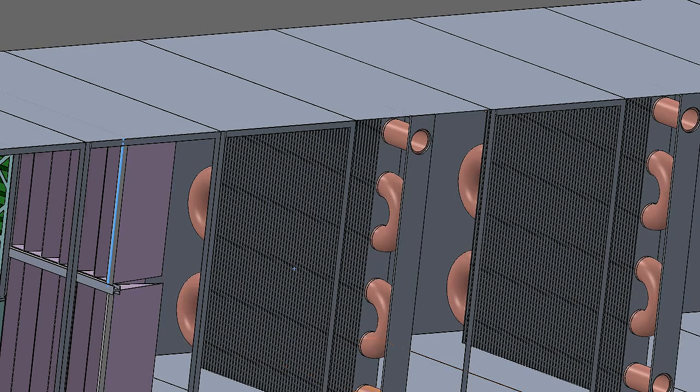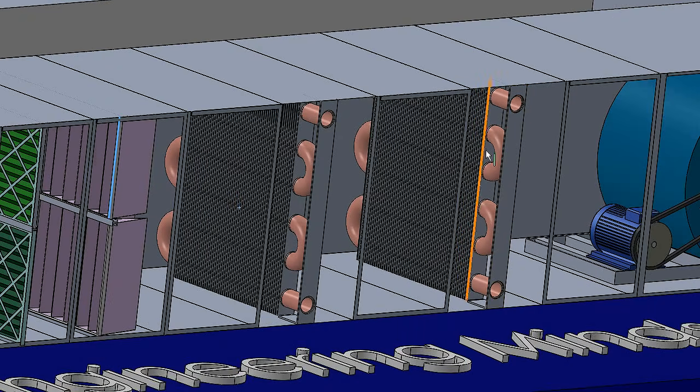With your heating and cooling coils, obviously the heating one is going to be connected to your boiler or your heating system. It could also be electric. It could be an electrical heater in here, certainly for frost protection that's sometimes used. And on the cooling coil here, this is what's going to be connected to your chiller or your chilled water system. If you remember back to the beginning of the video, that's what's coming off that riser, that chilled water coming in and passing through.